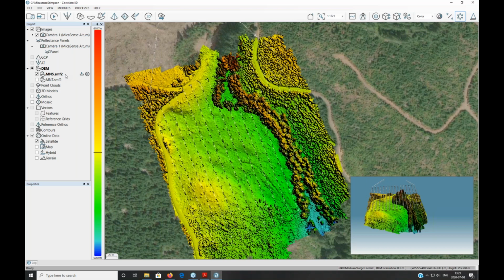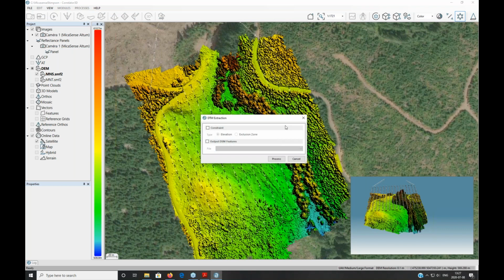specific raster file. So from the surface model, the user can also extract a terrain model. We have an algorithm that's going to try to remove all the elements that are not ground related, such as trees, buildings, cars, and all those other elements. So it's an automatic tool that will remove all the elements that I've just mentioned.